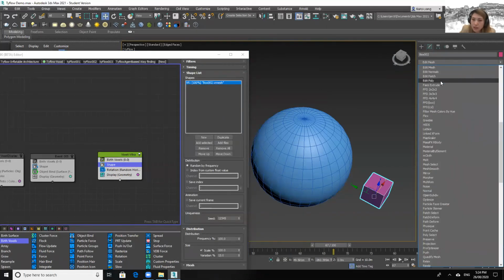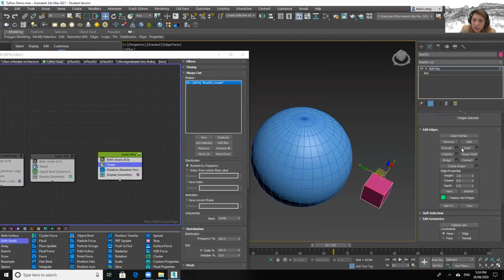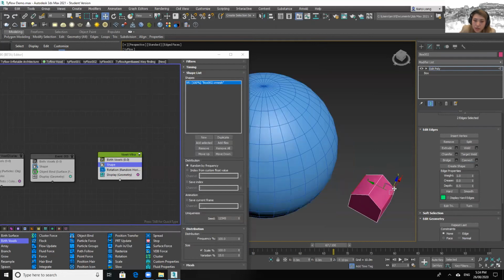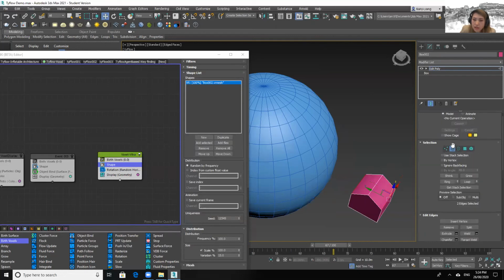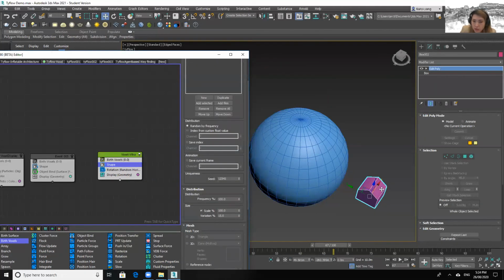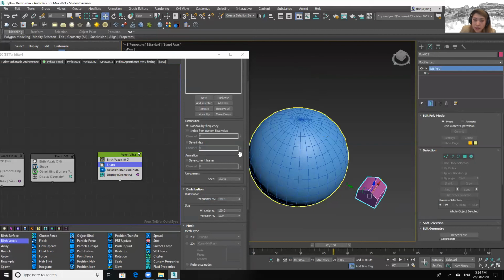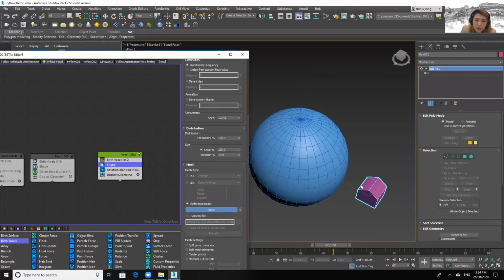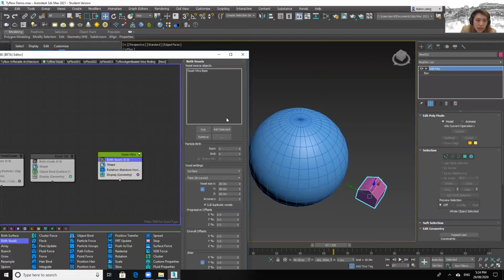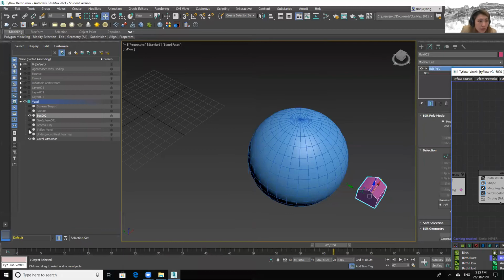And edit poly. We showed it, I think, last week. I'm going to create a little connect, and move these edges down. So this is kind of like a pitched roof house. I'm going to use that to replace the box I have. The quicker way to do the simulation is to right click on that and save it as a V-Ray mesh. But if you don't have V-Ray, I think that's fine. You can still use the reference node under the shape and pick that, and that shows the geometries. So, type voxels.